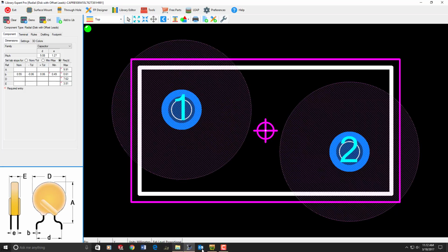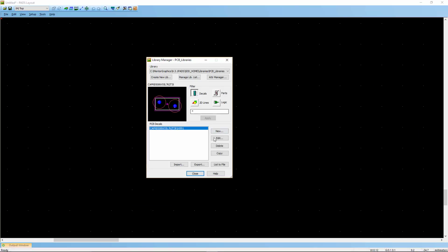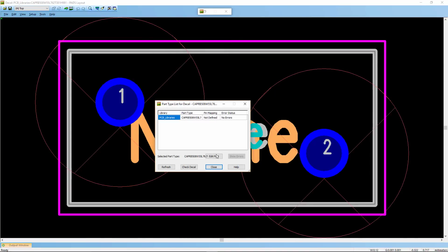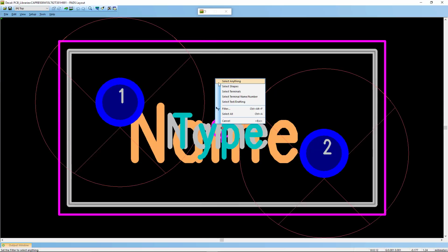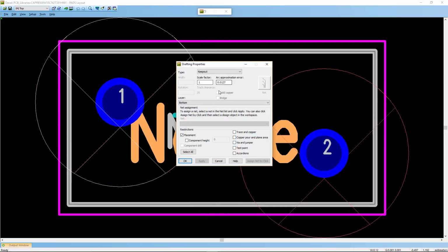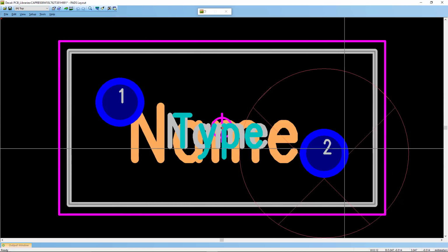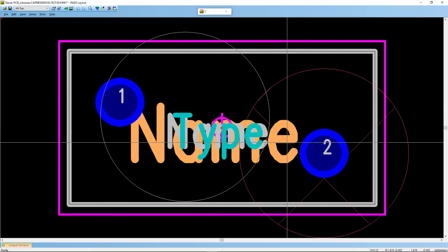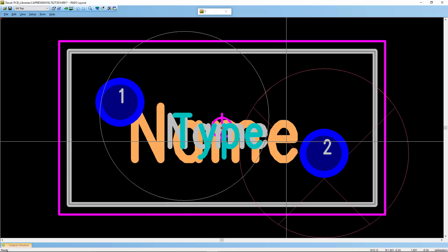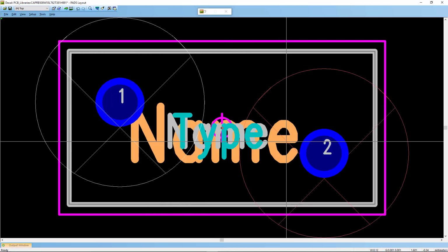We open up our CAD tool and open up the part. And if we select the shapes, we can see that the shape is a bottom layer only, and it's a placement keepout. It's not a trace or a via or a test point keepout. It's just strictly for part placement. Also, we can move the keepouts around as they're really not associated with the pad stack. They're just put in as drafting elements for the part.